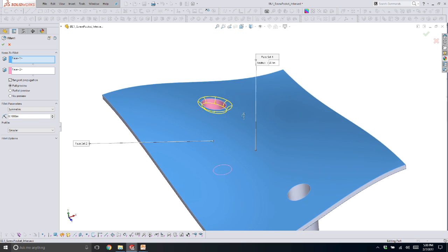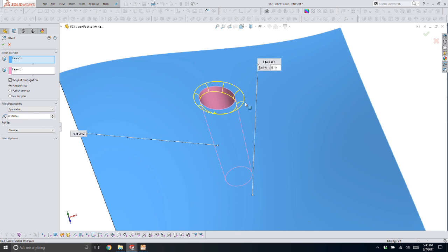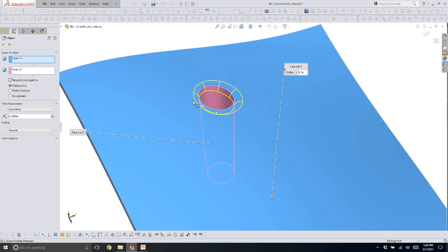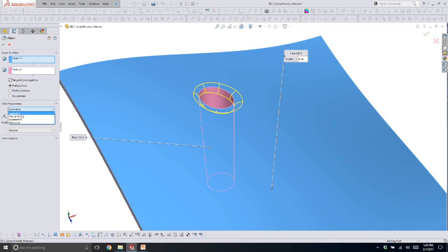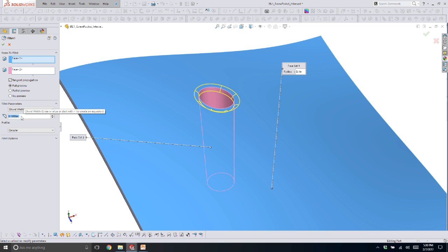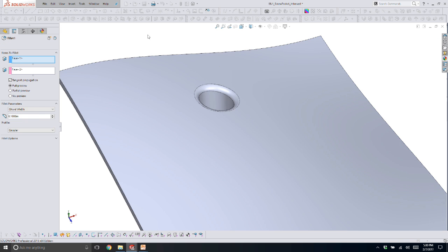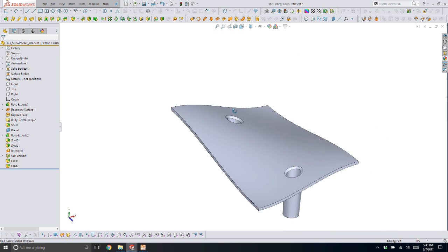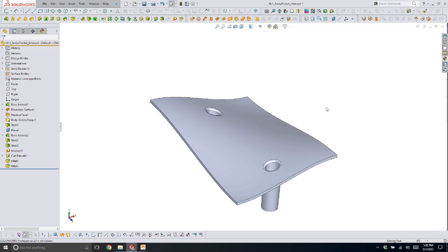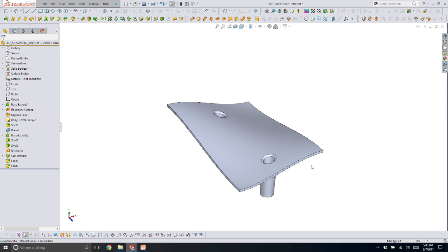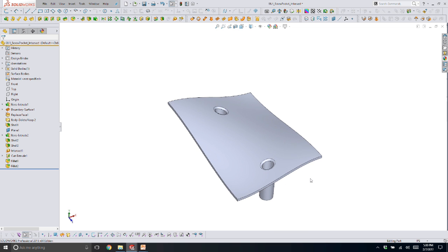So it's a symmetric fillet. You can see how the fillet gets large over here and is smaller over here. Designers love fillets that look the same size, even though the radius is changing along their perimeter. So change that chord width, and now it's visually the same size, and I've finished off this screw pocket. So if you don't have access to the original master model, not a problem. Just model your screw pockets, shell them, and then use the intersect to put the geometry back together.